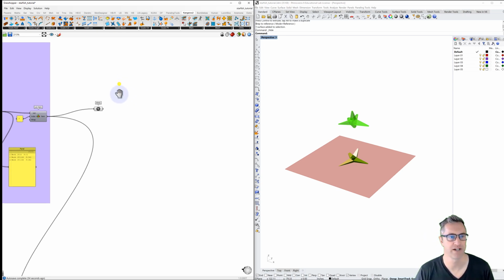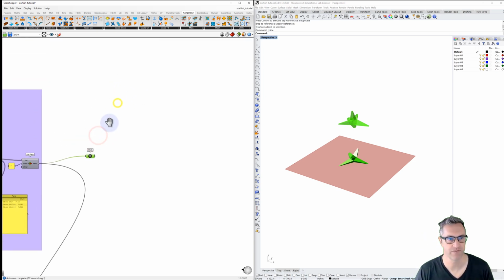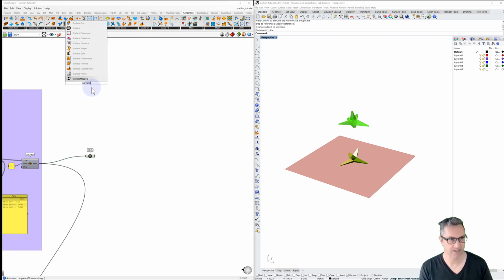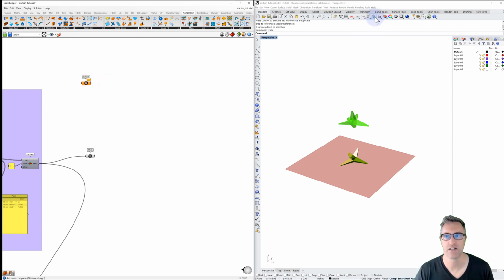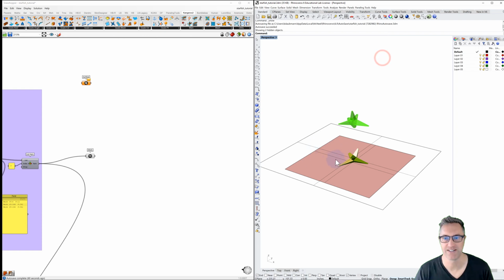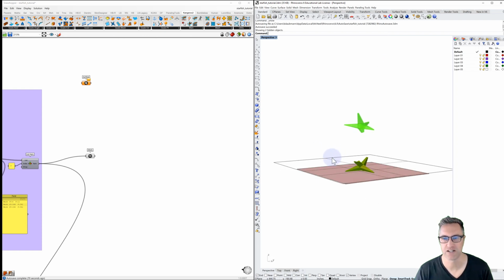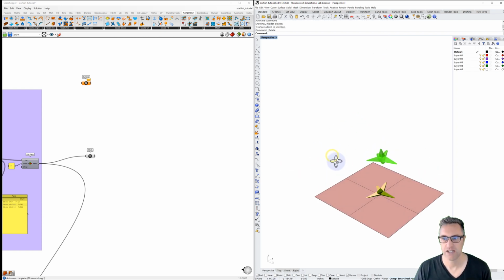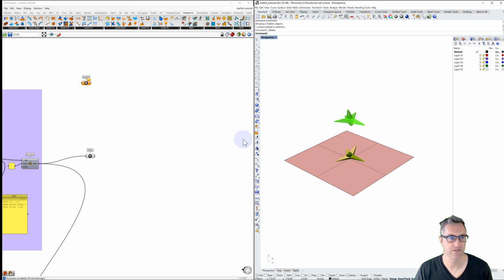Well, let's start with our plane. So that's the mesh that we're going to inflate against. Let's start with a surface, and for this surface we'll do a surface container. Let's unhide the plane that we defined previously that we're using for our first simulation. Let's set our surface container to be equal to that plane. We can then hide that object again in Rhino.